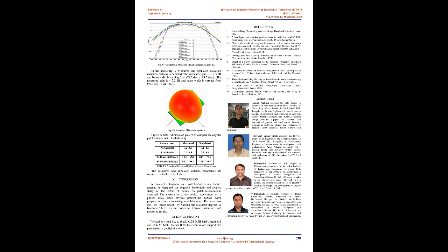The antenna has a very useful application as a phased array since cavities prevent surface wave propagation, thus eliminating scan blindness. The skin loss can be made lesser by varying the available degrees of freedom. There is close coherence between simulated and measured results.